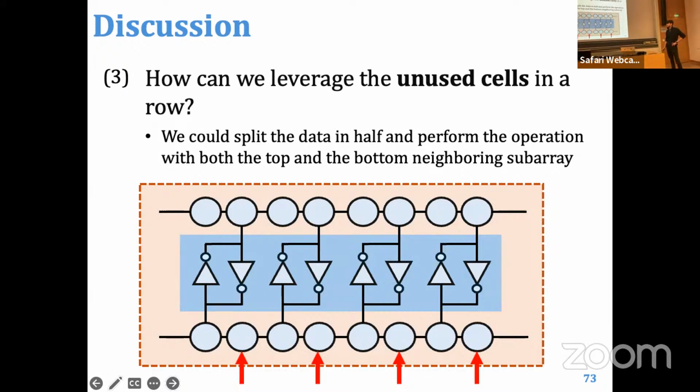Okay. I think it would be more beneficial to do a majority operation. If we change the DRAM, we should do a majority operation. But if we don't change the DRAM, we want to increase the success rate of this specific one. First, we need a way to put reliably half voltage on a cell, which is difficult in itself. I think it would be a really difficult modification to do. And then we will need sense amplifiers that actually amplify the difference better. If there is even the slightest difference, they will need to pull at the correct point. I think those would be the two main changes. Yes.